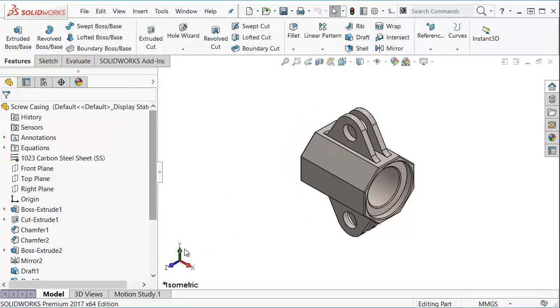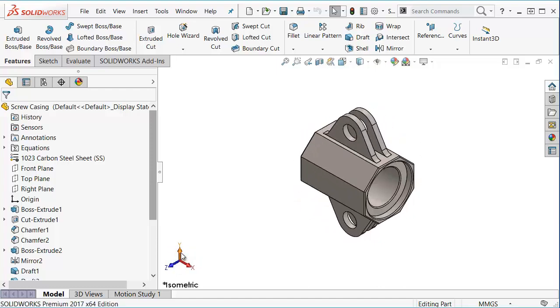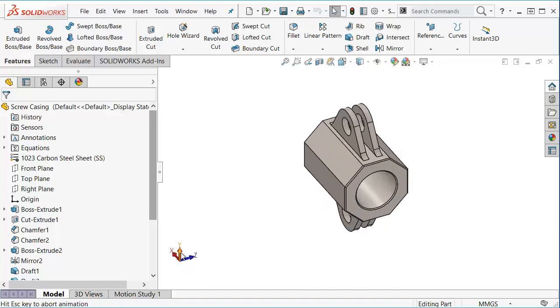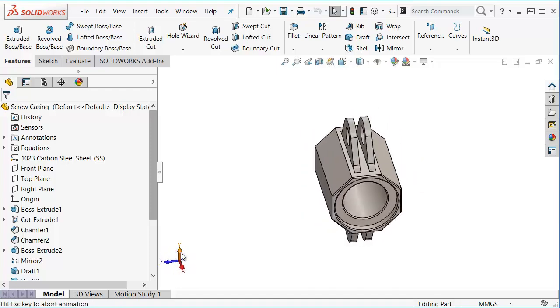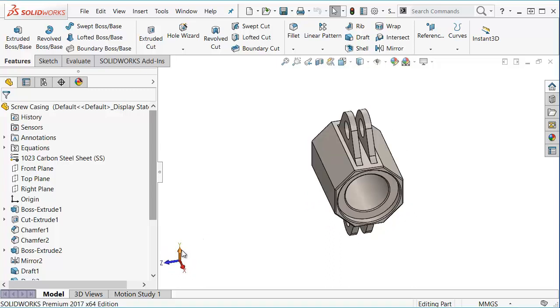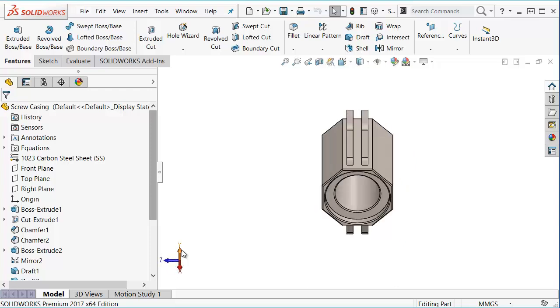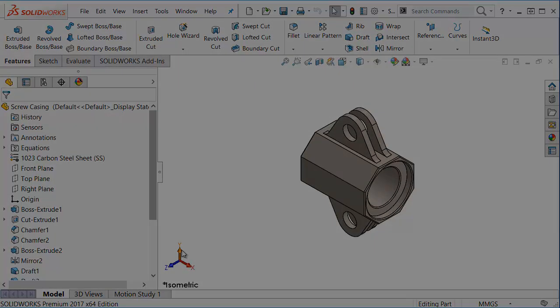If you hold down the Shift button and click on an arrow, it actually rotates about that arrow 90 degrees. If you hold Shift and Control, it'll go in the opposite direction. If you hold Alt and click on an arrow, you can see how it moves in small increments. If you hold Alt and then Control, it'll go in the opposite direction with those same increments.